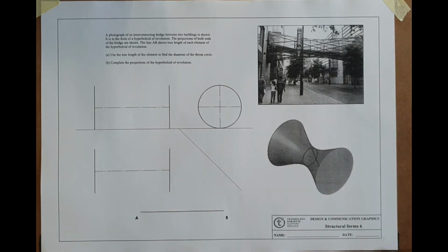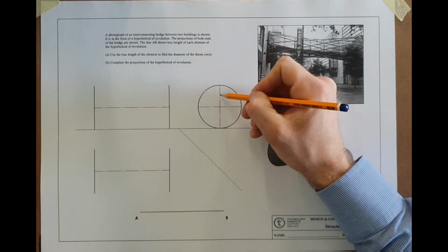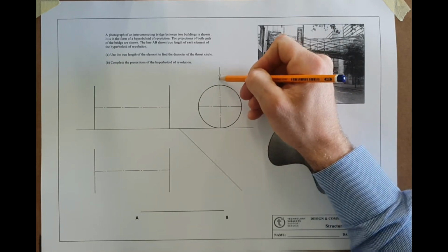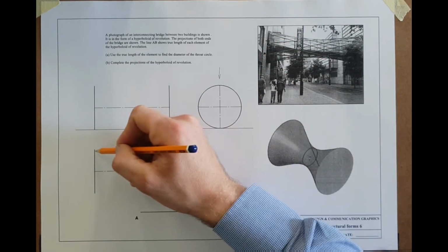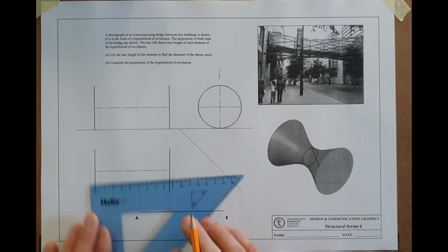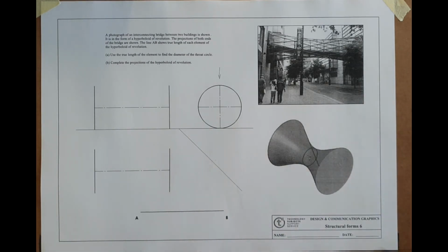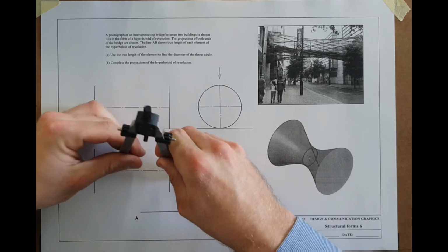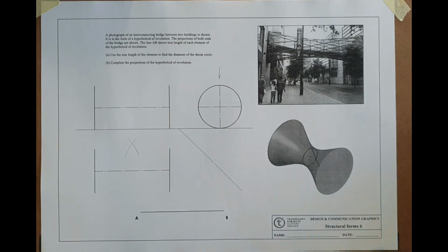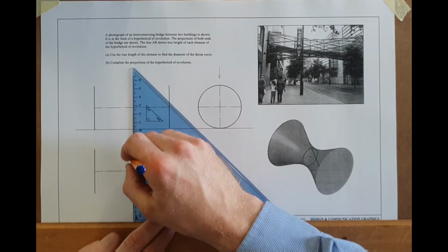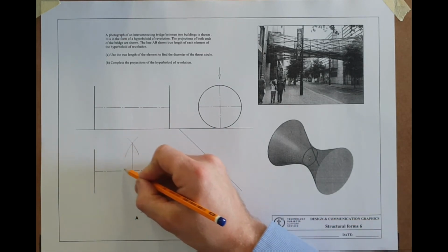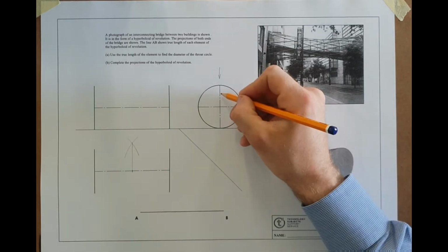Where do we start even here, right? The elements are, we'd like a throat circle here, and we'd like to see the element crossing. And if it was crossing there and we look down on top of it, we'd see it as a true length here, crossing. So that's how I'm going to start this. Now, I just measured the length of this, and it's 87 point something. Can't find the centre of 87 point something. So I'd like to find the centre of the drawing, and that's easily done. There's the centre. That's where the throat circle is going to be, but that's where the true length elements will cross, one in each direction, because I'm structuring it this way.